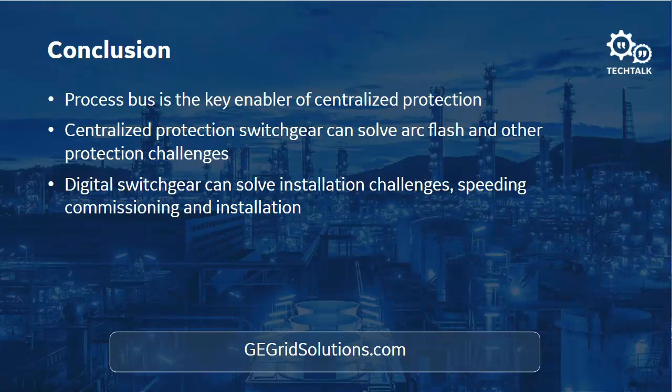So here's a question. What are the distance limitations between the merging unit and the central protection relay? Typically, on our relays, the Ethernet connection between the relay and the merging unit is a fiber optic Ethernet. So if we go point-to-point between the relay and the merging unit, there is a dispersion limit of the fiber, right?